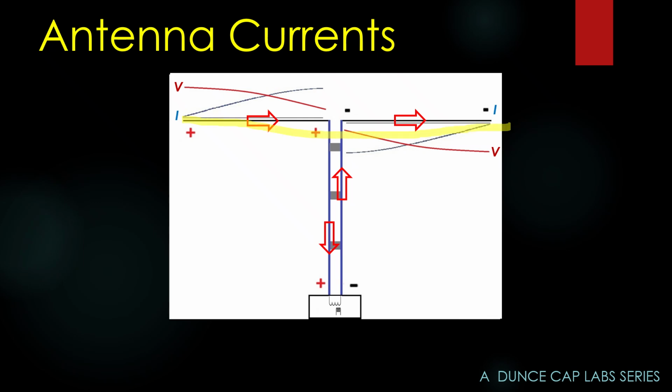There we go. We have a great voltage gradient across the antenna. This means there's an electric field generated across the antenna. This electric field is horizontally polarized. That means the antenna, we say, is horizontally polarized. It is generating magnetic fields from the current in the antenna. The magnetic fields are vertically polarized. The electric field is horizontally polarized. So therefore, we have a horizontally polarized antenna.